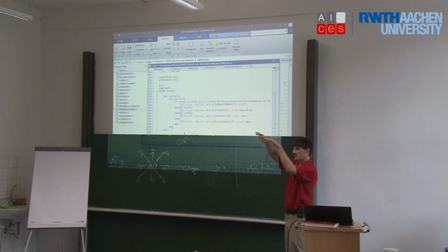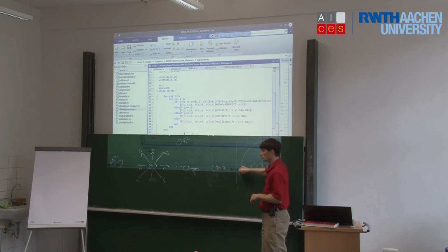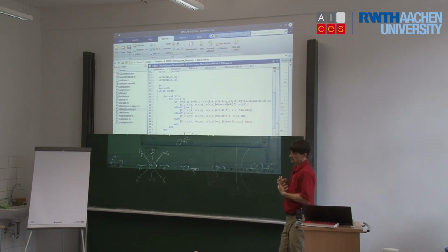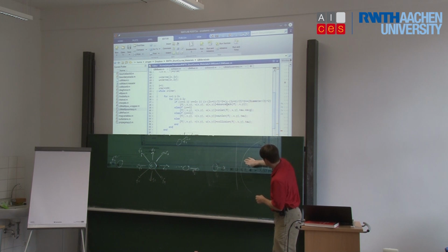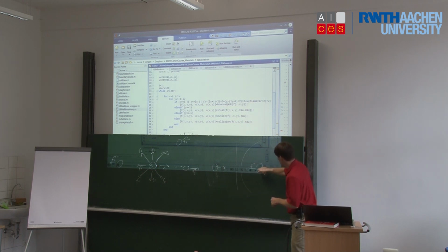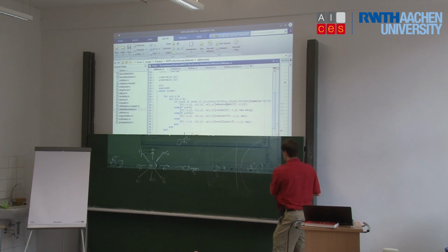Now, if we want to accurately represent our ellipse, we will have some sort of a curved boundary, and this is not going to be located halfway in between. And so there is a condition that you will see in the code that's called interp bounce back, and if you look at the Lattice-Boltzmann literature, it's called interpolation bounce back boundary condition. Basically, it finds this location and says, well, okay, here I have this node that moves towards the boundary. Here I have another node. Okay. And so if the boundary is closer than halfway between these two nodes, then the reflected value will be interpolated between this value and that value, because this one will move this direction, this one will move, and so the resultant value will be actually somewhat of a combination of this one and that one.